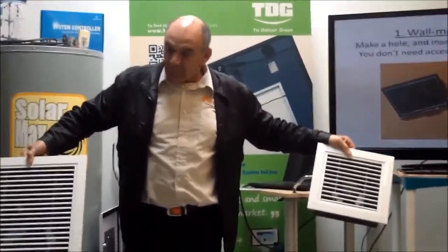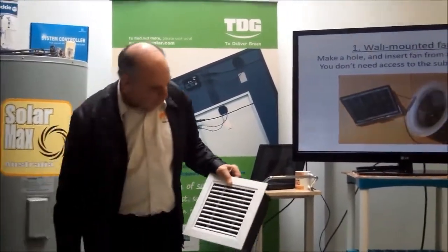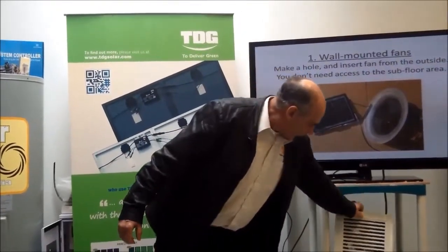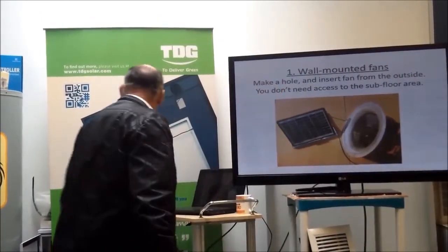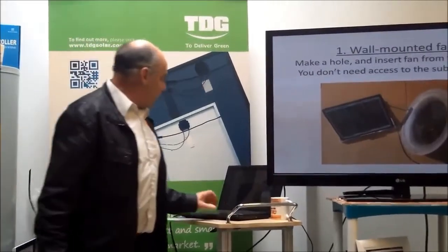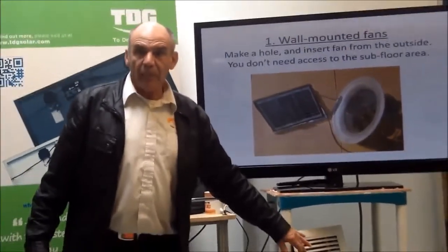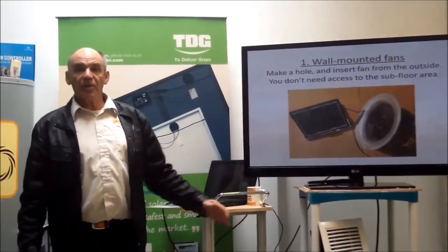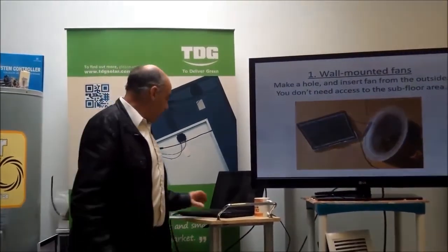They've both got the grill. So there's one thing that you could ask for, and that is about the bushfire mesh. These have a wire mesh to stop moths and things getting inside, but we can also replace that mesh with a finer bushfire mesh, which means you can put them in bushfire rated areas.